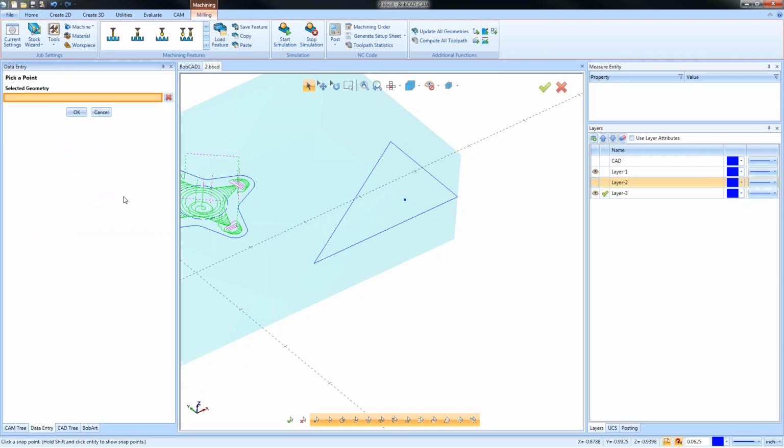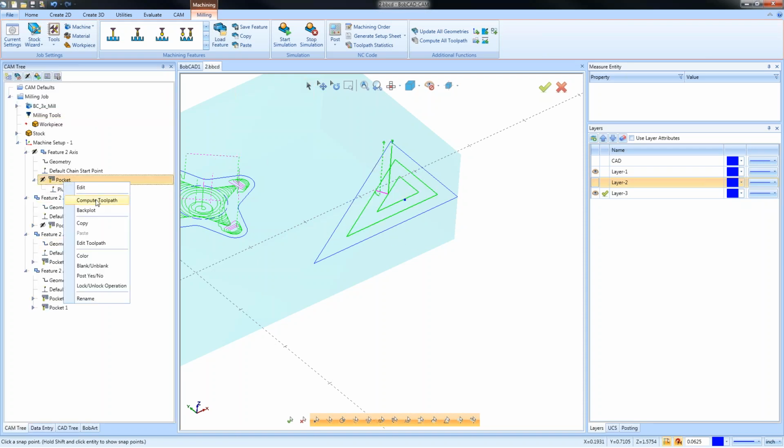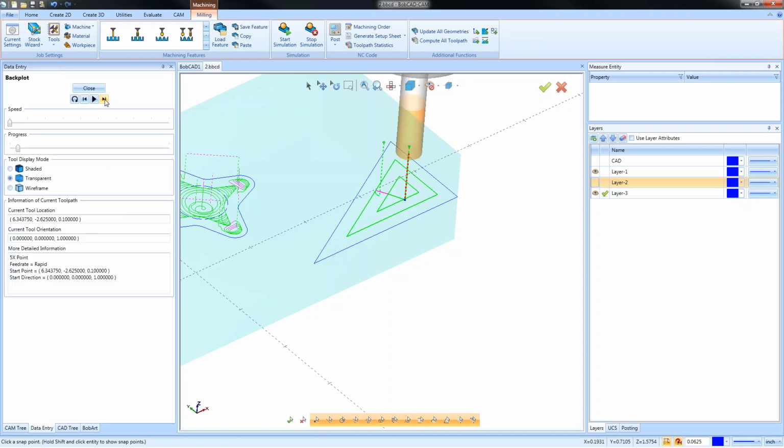We're going to pick our plunge point. It's important to understand that for some routines where the point is located in Z matters. So if you do an adaptive routine, it's where that point is in Z. But we'll pick this location and we'll recompute here. And now you can see the tool starts at that point location and then connects and works its way out. Okay. All right. So that is a little bit about the pocketing. We have our start point location.